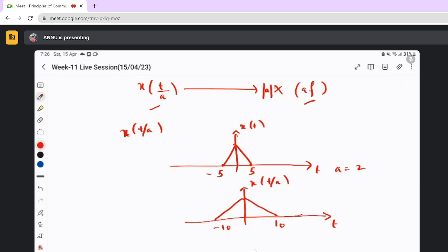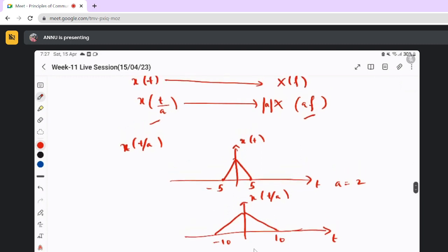Actually, I am referring to frequency multiplication in FM modulation. We have to scale the frequency. For example, whatever signal we give with a frequency of f, we have to have 2f, f square, or f cubed. So just look at this expression from the other side. How do you get f square? It won't be scaling if we are having the square of the frequency. That is something called a frequency multiplier. It is frequency multiplication, not scaling.